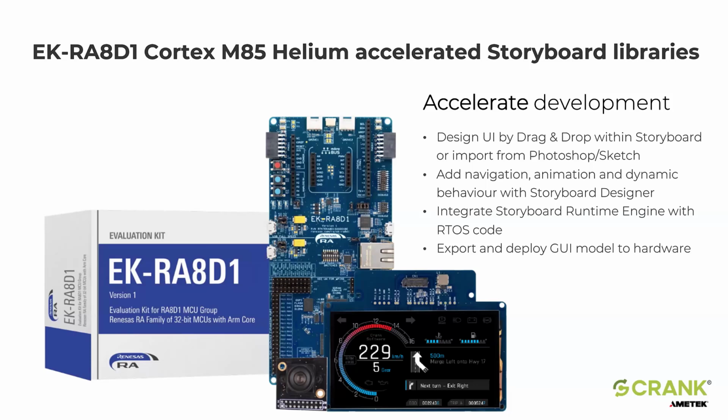And we'll show you how we've worked with the ARM guys to integrate the ARM 2D library. So this is the acceleration library from ARM, which leverages the Helium vectorization extensions present on the Cortex M85. And we're leveraging that, again by using that framework, to accelerate some of the drawing operations, blitting, masking, clipping, that sort of thing.